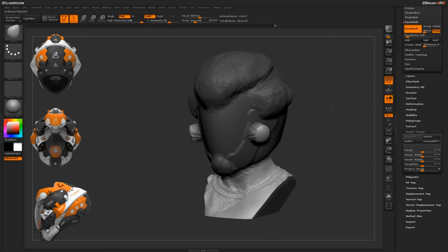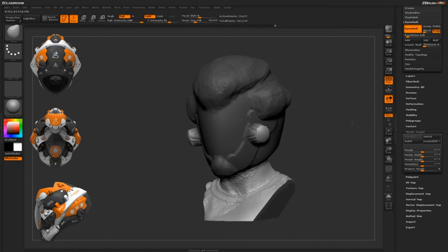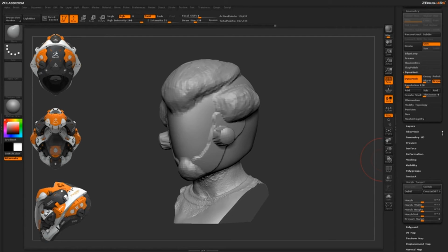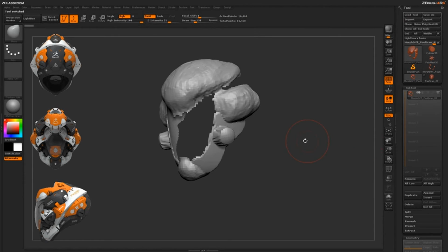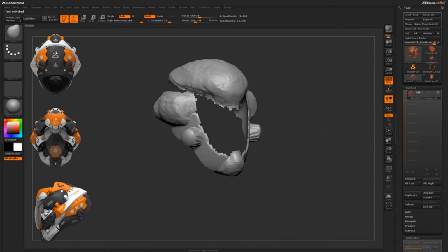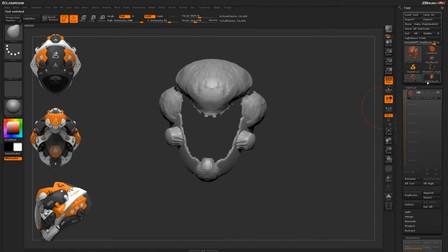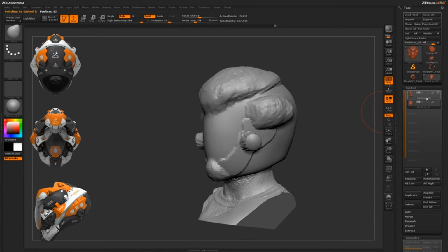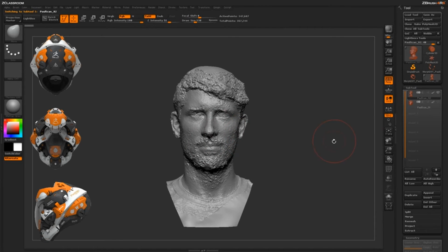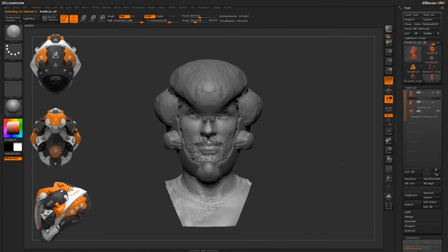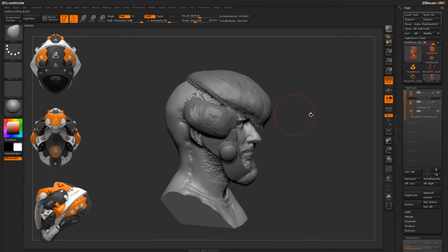And then after you have your panels and everything sorted out the way you want them, just clear your mask and then come over here and just click that create difference mesh button there. Now if we go up to the top, you'll see I have this nice mesh that's been generated from that actual morph target. So then I go back to the scan of Paul here and just select that, so I just see Paul's head, and I can just append that morph difference new tool right in, and so you can see now I have the head with that geometry on it.